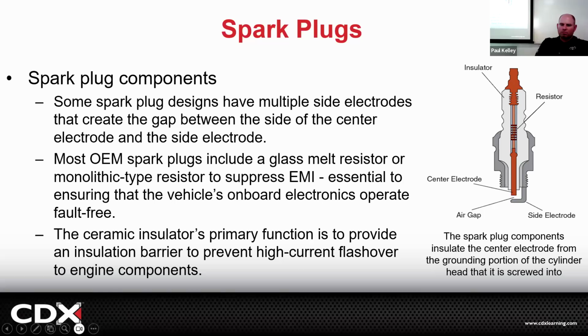So if we were looking at this, oh, and sometimes they even have a resistor or some other little details. When I go to change spark plugs, I always recommend OEM, whatever the car came with new. I don't try to put in some upgraded. I don't try to change it to hotter, to colder, to whatever. Just whatever OEM was. If it's a Ford, it's getting Motorcraft. If it's a GM, it's getting AC Delco. If it's Japanese, it's getting either Bosch or Denso, or if it's German, it's probably Bosch. Some take NGK, another Japanese brand. Whatever OEM is what I run.